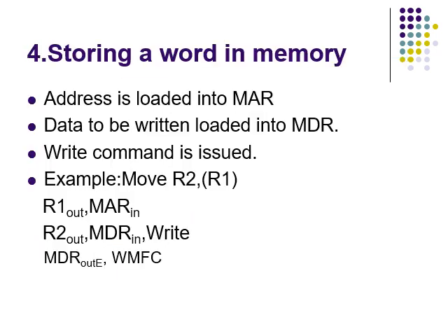Now, let us discuss storing a word in memory. Writing a word into a memory location follows a similar procedure. The desired address is loaded into the memory address register. Then the data to be written is loaded into MDR and a write command is issued. Hence, executing the instruction Move R2, (R1) requires the following sequence.